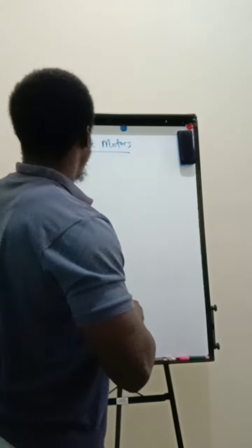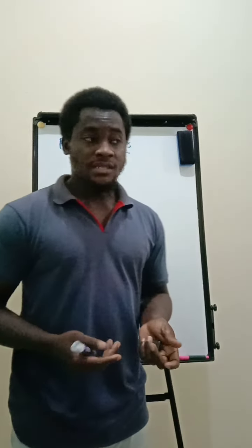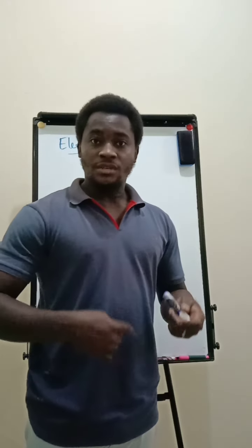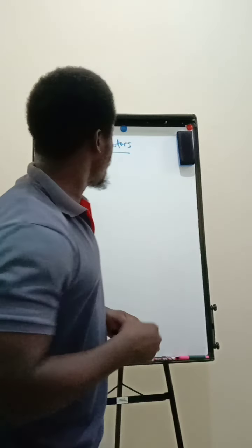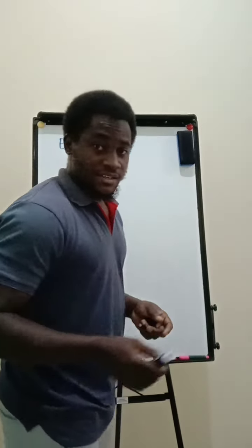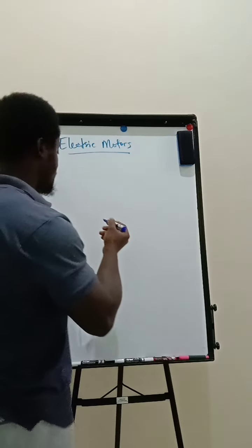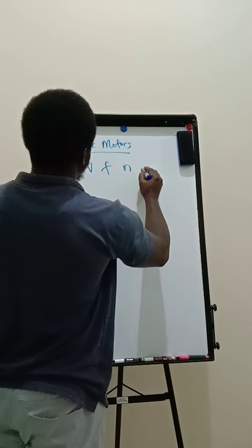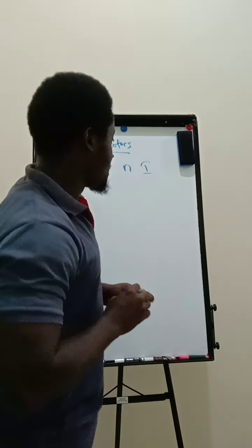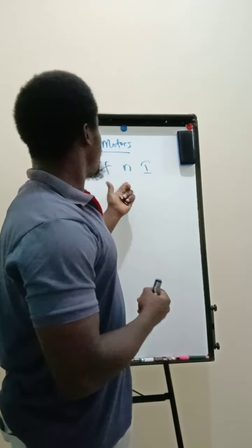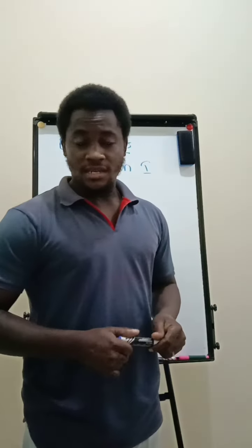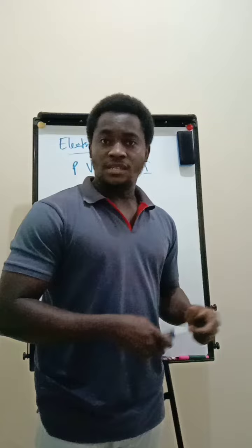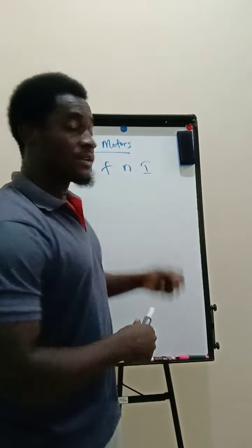Basically, we are going to be checking some points like the mechanical part of the electric motor. Make sure that the rotor is rotating freely, which is very important. And then check also the nameplate of the electric motor. On the nameplate, we have several parameters like the power, the voltage, the frequency, the speed, and the current. We take down all these different parameters and make sure that they are equal to what is written on the material submittal. Based on that, we know it conforms to the standards or what we submitted to the supplier. This is what is delivered on site.